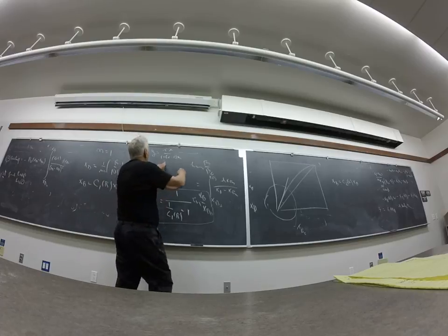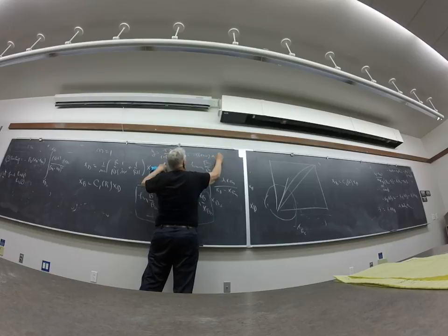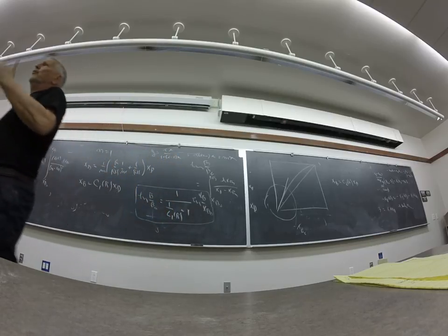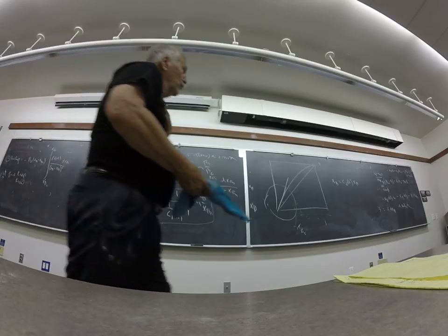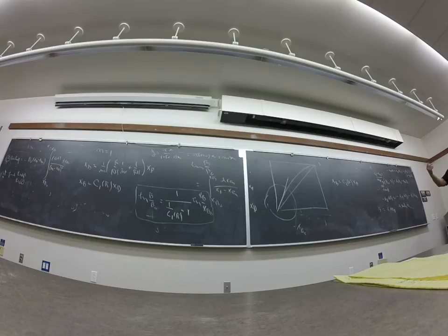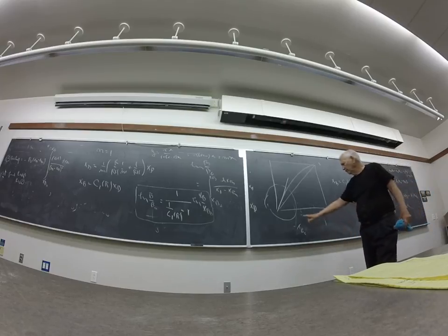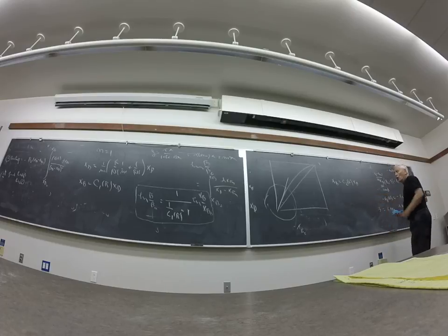But for x small, this is basically alpha at x equal to 0 times x, which I've chosen to call mx, simply because I've always called distribution ratios m or k or something like that. Okay, so that's what it is. Take the slope of that line, you've got the distribution ratio at the very dilute case. You might get away with this up to, well, I don't know, maybe up to 20% or so. It's hard to say. But it's so cheap that you'd be crazy not to use it if it's close.